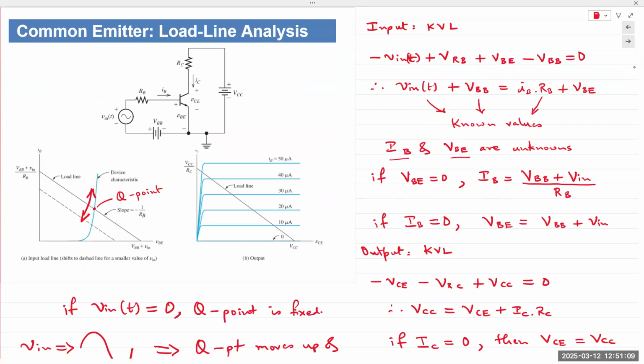Anything we do with the NPN examples applies equally to PNP, except holes are switched for electrons and vice versa. Voltage polarities are flipped and current directions are reversed. In an NPN transistor, current flows out of the emitter, hence the arrow points outwards. In a PNP, the current flows into the emitter, hence the arrow points inwards. So again, it's just reversed.